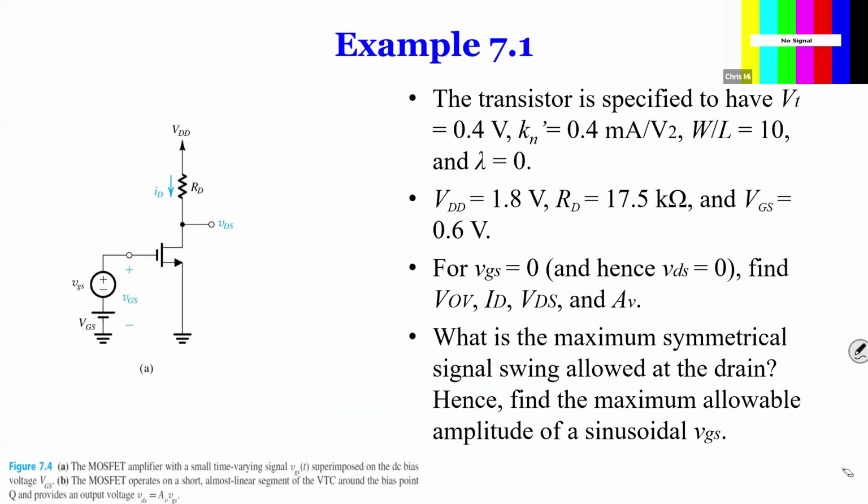So that's not going to work. So the maximum value of your AC signal to keep the transistor in saturation is your input range. And of course, that also gives you output range. And from input range you can find output range, and for a given output range you can also find the input range. And they're corresponding to each other.